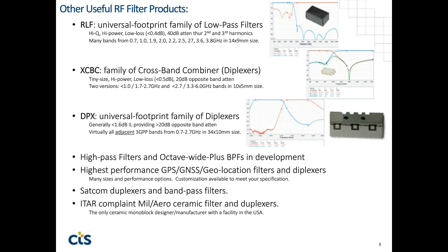But it's also important not to presume that the power on the data sheet is in fact the limit of what even the given filter can handle. In some cases, we have spec'd the data sheet at the limit of the power that the filter can handle. But in some cases, we simply specified what I would call the useful power.